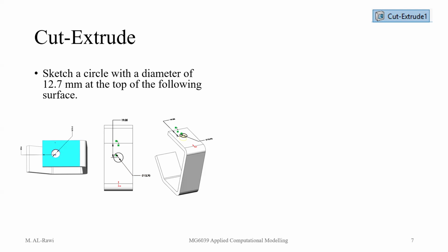And if you want to use lines to make your life easy, make them construction lines. But try to learn how to use the center, because the mouse can sense the center line and that disconnected line to tell you, hey, you're on a straight line. All of you made the circle, or do we still have one? What's happening?